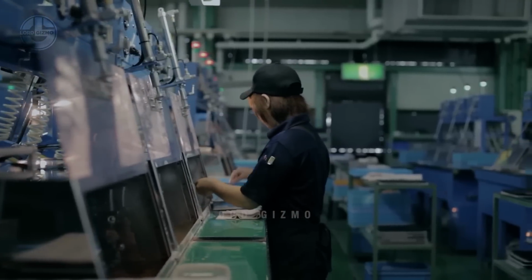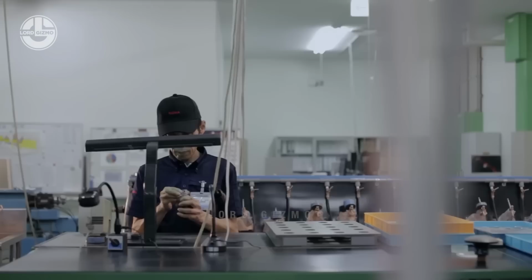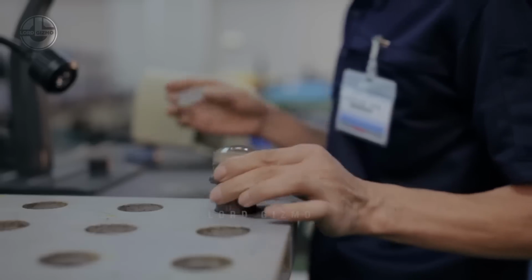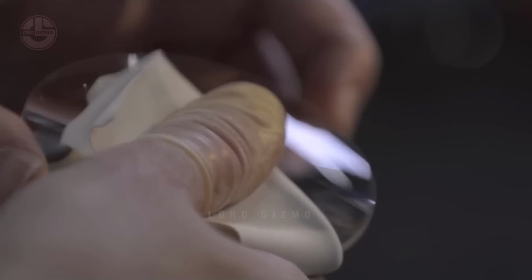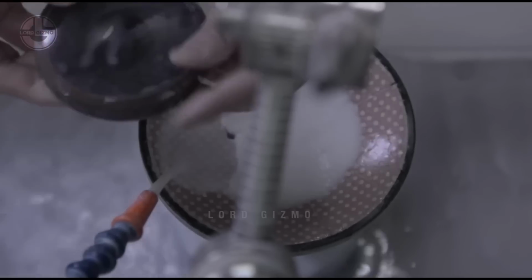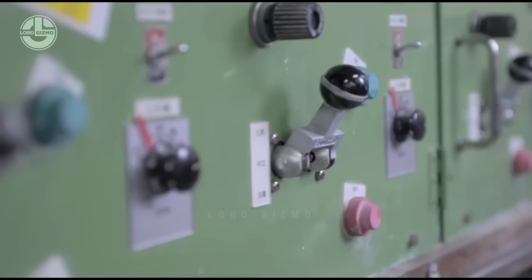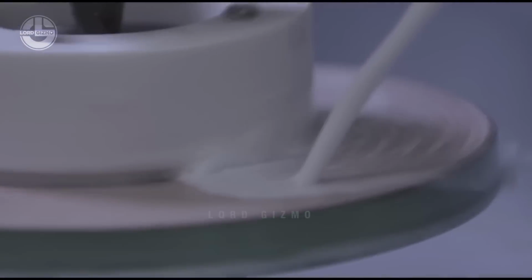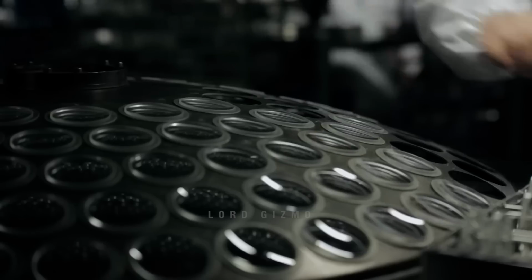Glass polishing is a slow procedure that requires lenses to be oscillated back and forth against a spinning polisher for hours at a time. The lenses emerge from this process with a gleam, their surfaces smooth and their profiles perfectly curved. After 3 hours of receiving this protective finish, the lenses are cleaned to remove any residue. Each lens, whether concave or convex, undergoes a rigorous inspection and cleaning process. The stakes are high, as even a single speck of dust could compromise the optical system, affecting the image quality.